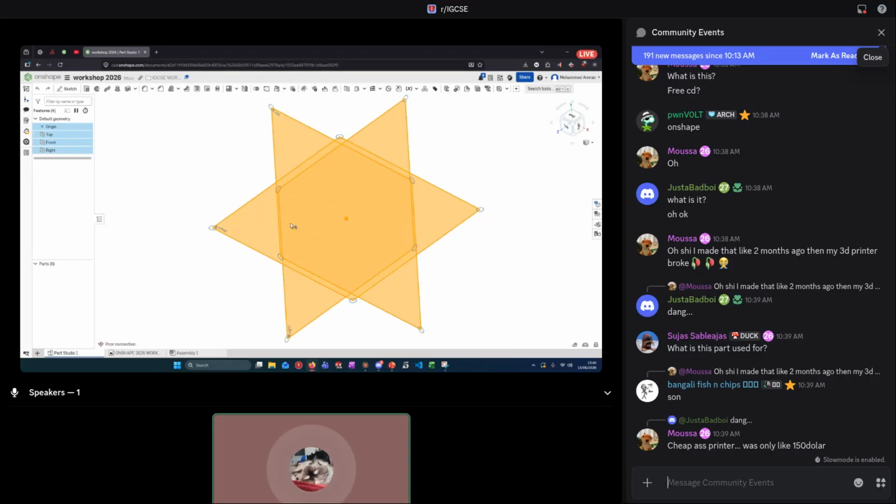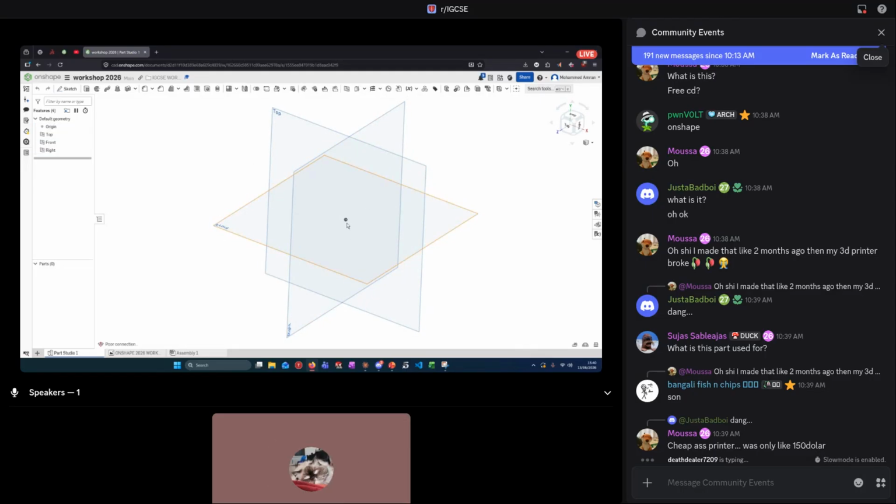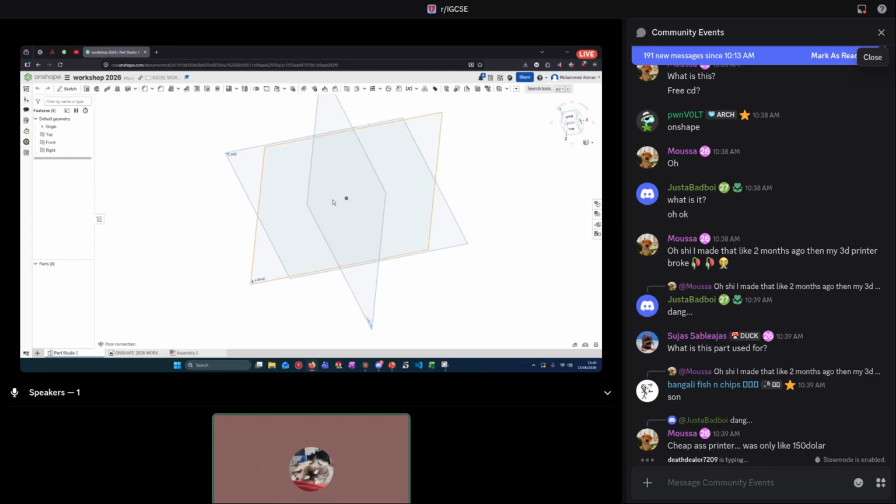Once you've selected something, like look, I've selected 3 things. To deselect them, you just click on an empty spot. If I have anything selected and I want to deselect it, you click at an empty spot and then things will be deselected, because some actions can only be made with your pointer. So get comfortable with that. You have these planes in your window, top, front, and right. You have this cube right here, middle mouse to rotate around, middle mouse plus control to pan around. So just move around, get comfortable, okay?